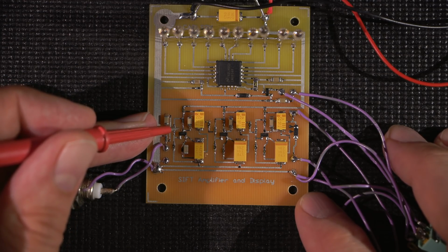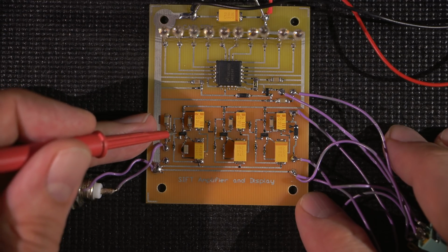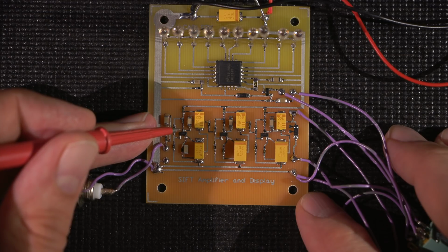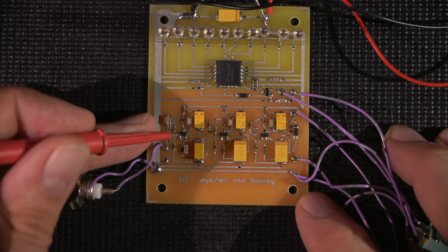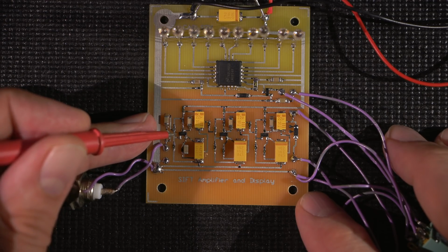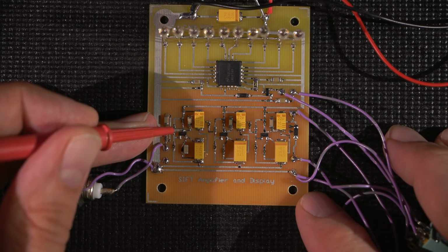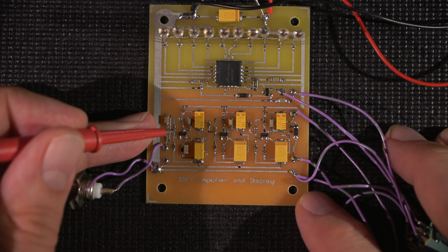Now again, you can cheat. You can actually use the circuit within the amplifier itself to see if it's amplifying just by probing this. Say you had a vacuum tube oscilloscope or just an analog oscilloscope of any type, whether it's solid state or vacuum tube, and you couldn't get a measurement at this point, you can very easily verify that by going to this point here, and you're going to see some amplitude, because that would tell you right there that that amplifier is working, right?